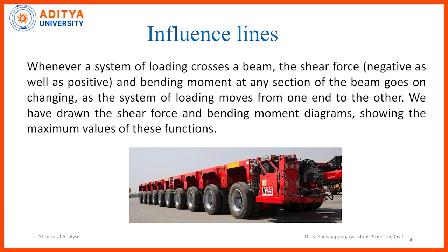But in terms of bridges, when a vehicle passes from one end to another, there will be a moving load. According to that moving load, the shear force and bending moment at any point are not constant. They keep on varying depending upon the vehicle loading condition and location. So ILD is particularly about the moving load concept.